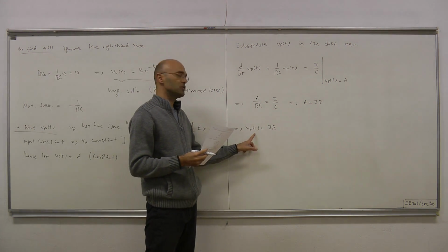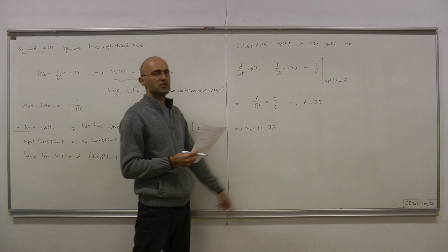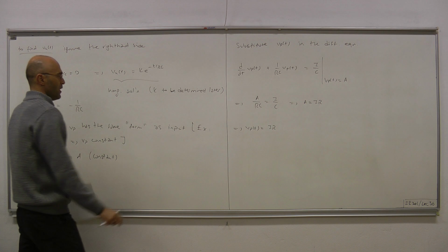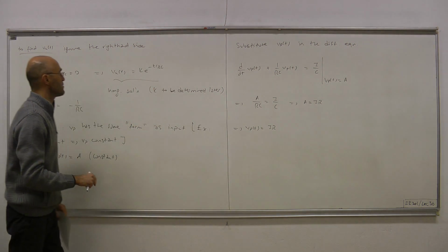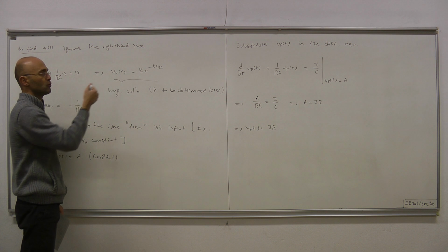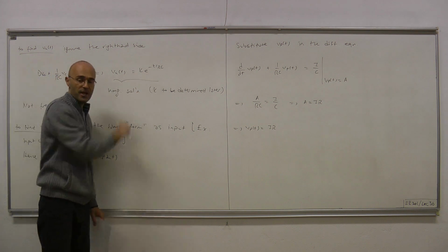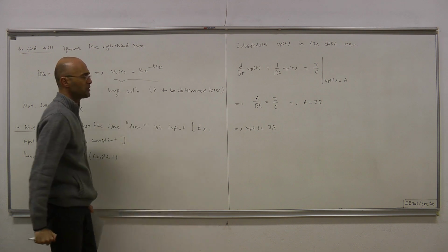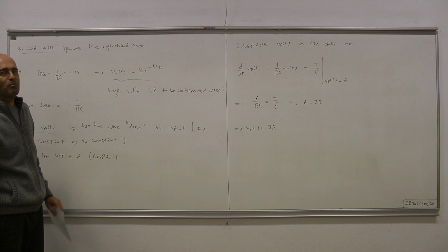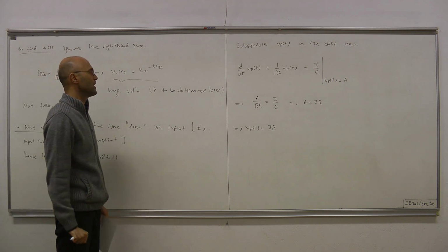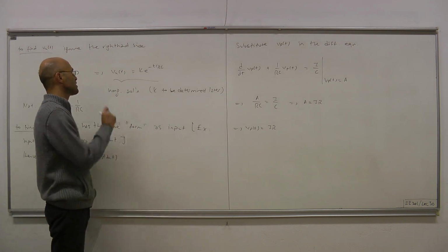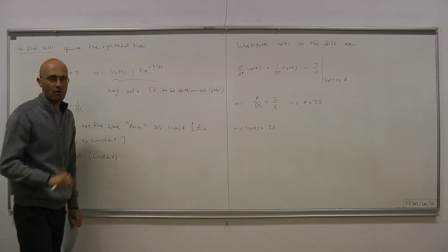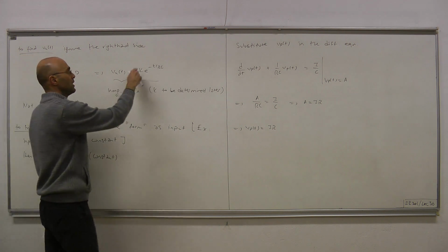At this point, the particular solution is known because I is known and the resistance is known. Now, we have the particular solution that's determined completely, and we have the homogeneous solution that's partially determined. We don't know yet what this K is. To figure out K, we combine the homogeneous and particular solutions. We sum them up to obtain Vc(t), the overall solution. And at that very last step, we subject that overall solution to the initial condition constraint, which in this case is 0. And that will give us what K should be.